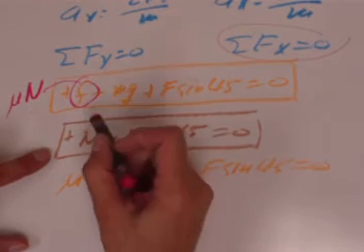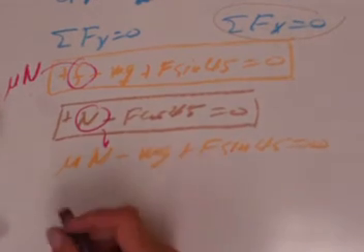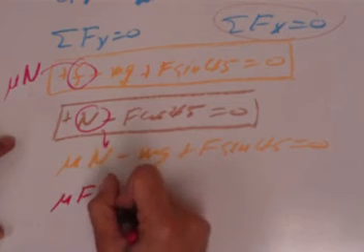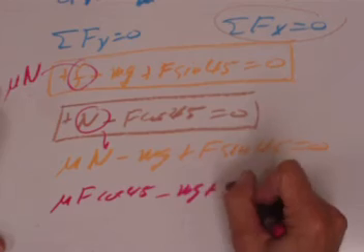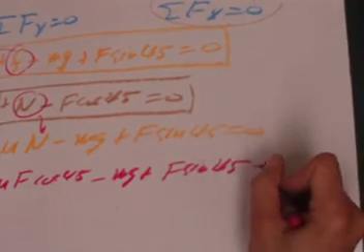And now what are you looking at? Well, you have the normal force from right here. So you can do a bit of algebra and actually get yourself one big equation. In particular, mu, if I solve this for the normal force, I'm going to get F times the cosine of 45, minus mg plus F times the sine of 45. All that's equal to 0.